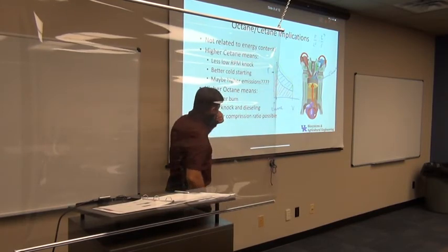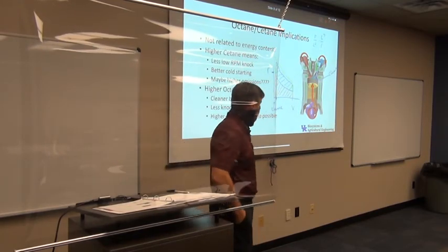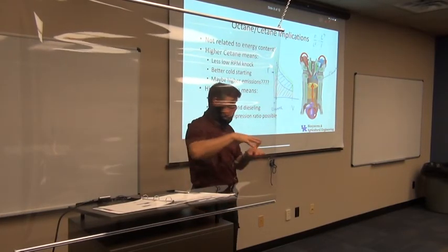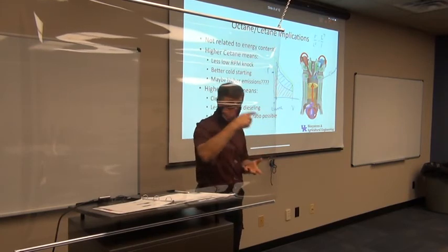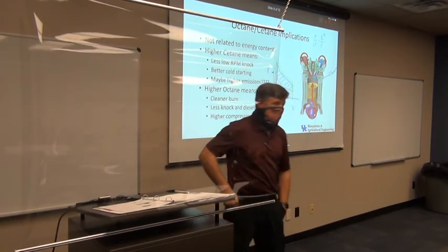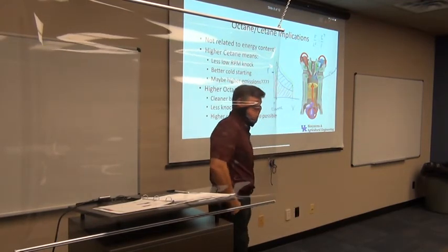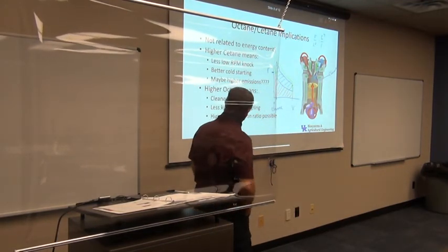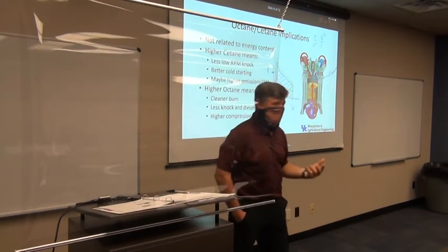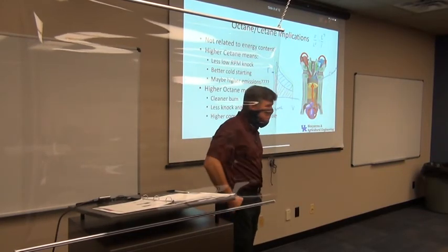So higher octane can mean a cleaner burn. Because I'm not burning too early, I'm burning at the right time, so I'm operating that engine efficiently, I should get a good burn. I'm going to have less knock and dieseling. That's a kind of funny term, because octane isn't a compression ignition thing, but we talk about a spark ignition engine dieseling.